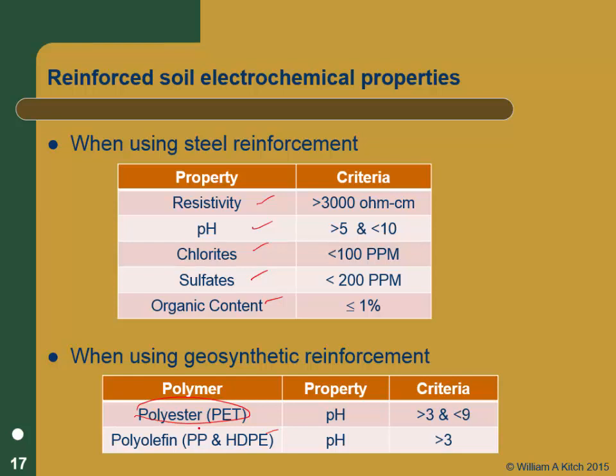This is a very low pH, so this is probably something you're not going to run into. This becomes important if you're designing systems for mine tailings, or heap leach fields for extraction of minerals, or any kind of systems where other chemical processes are going on.